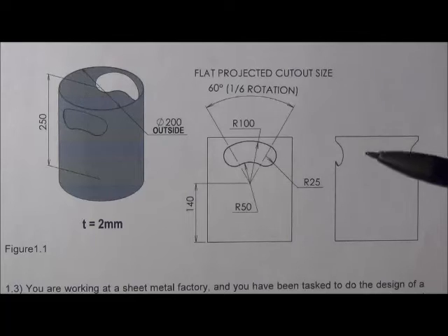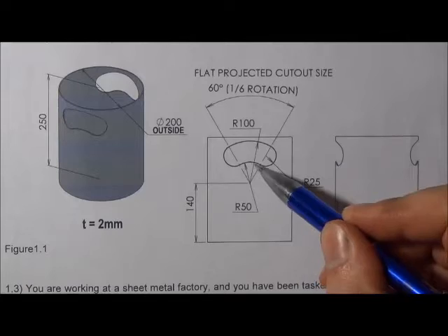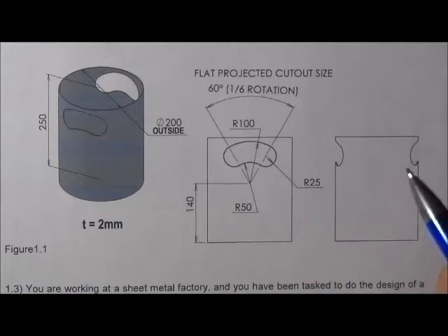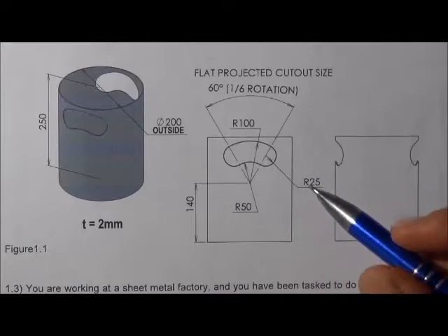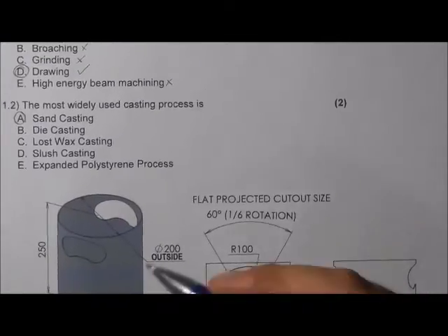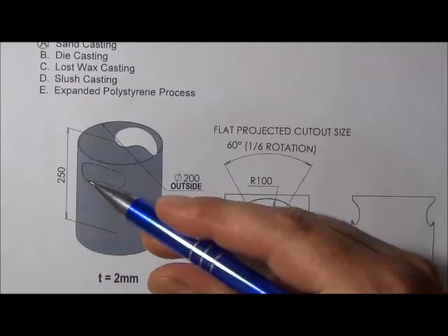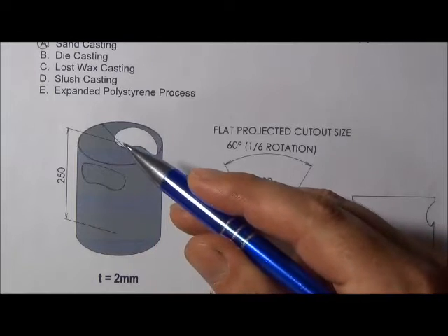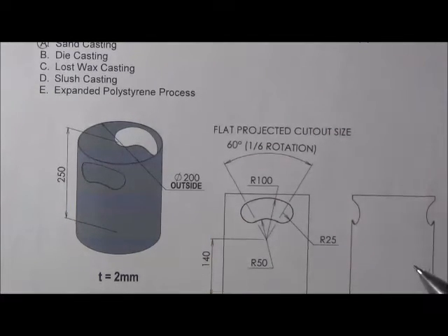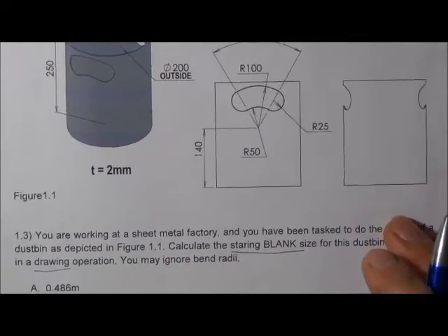That's why question 1.5 actually says, which we haven't done yet, calculate the force for cutting the handle out. So basically the starting blank is this starting volume of the cup without the removal of the two handle holes. And that must be equal to the volume of the flat disc that we use to make this component of.